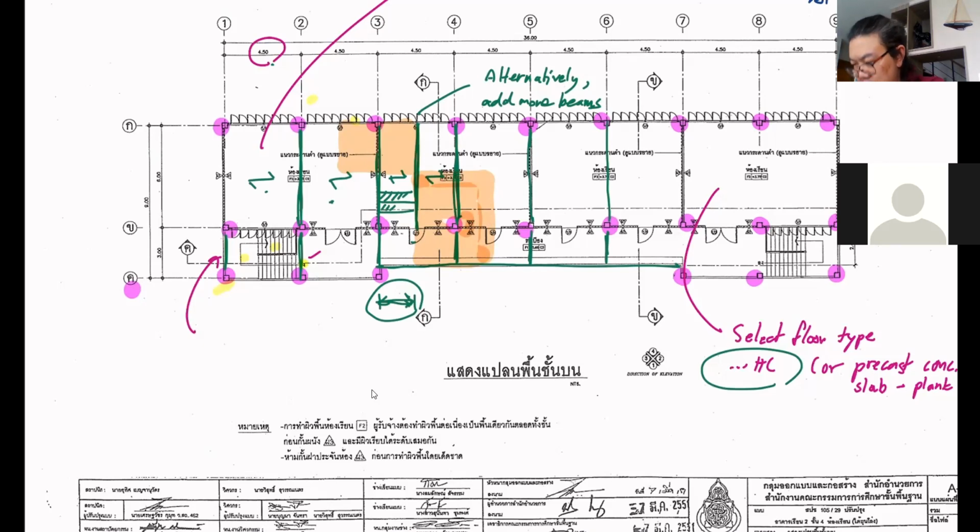And when you look at the floor itself, the floor system becomes the plank system, with the plank being 4.5 meters long. And after you have checked your load, it's going to be the dead load from the floor, correct, and then the live load.